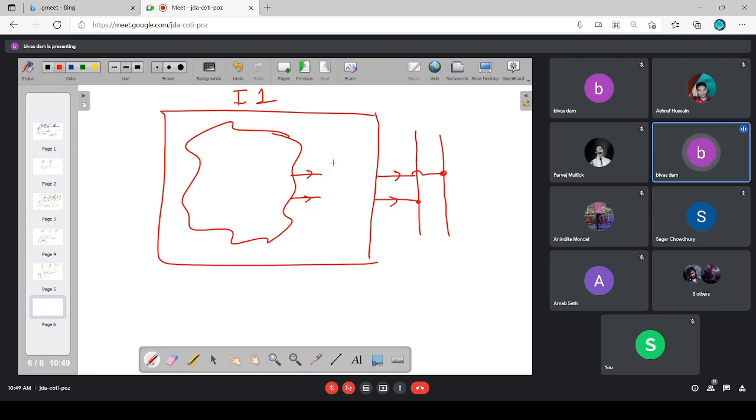What we'll be doing is, here one tri-stated TTL inverter is there, and another tri-stated TTL inverter is there. It is having one enable input, it is also having the same enable input. Now, if this enable input is 1, that means its output will be either logic 0 or 1. Similarly, if this enable input is 1, this output will be either logic 0 or 1.